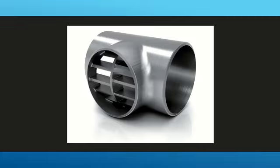This is a barred T. Actually, a barred T is a specialized pipe fitting with internal steel bars welded across the branch outlet, used in piggable pipelines. This is to block the pig from entering the branch while allowing fluid to flow. Are you following me? I'm sure you will find my discussion a very interesting topic.